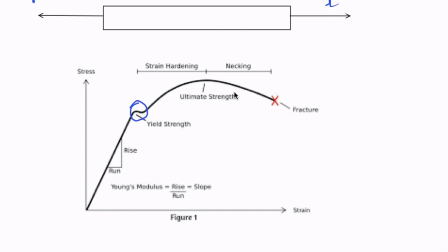If it is a brittle material, there will be no yield point. Instead, we will have a sudden and catastrophic failure of the material at ultimate strength. So in case of brittle materials, we consider ultimate stress as the limiting factor. Here we are discussing ductile material, but there will be certain situations where the material may fail below its yield point, somewhere within this area.